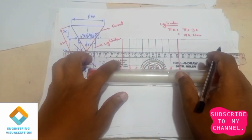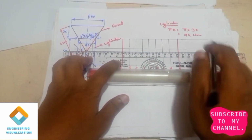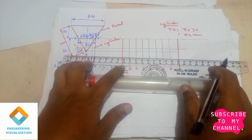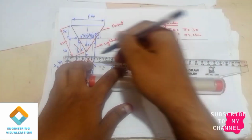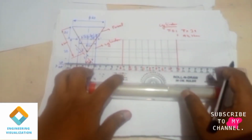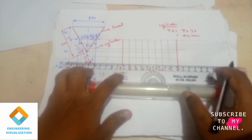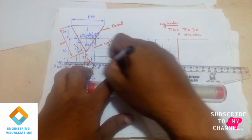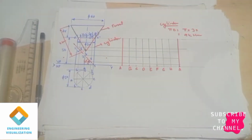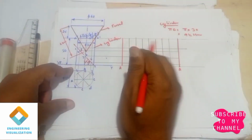Okay, from point 2 also you do the same thing, and from 3 also the same thing. So this cylinder and prism will be constructed in the same manner, guys, because all the cut points are occurring at these vertical edges. So no need to measure, just draw the projection lines and then now you mark.